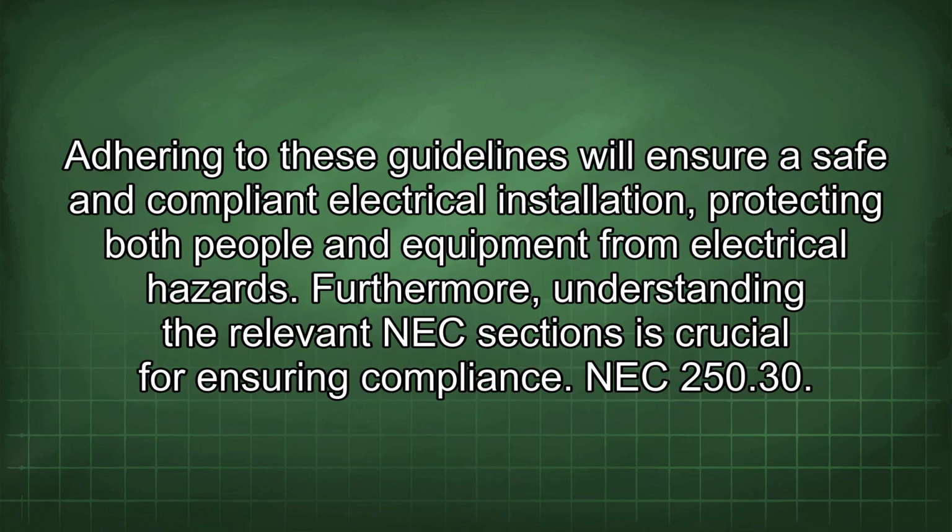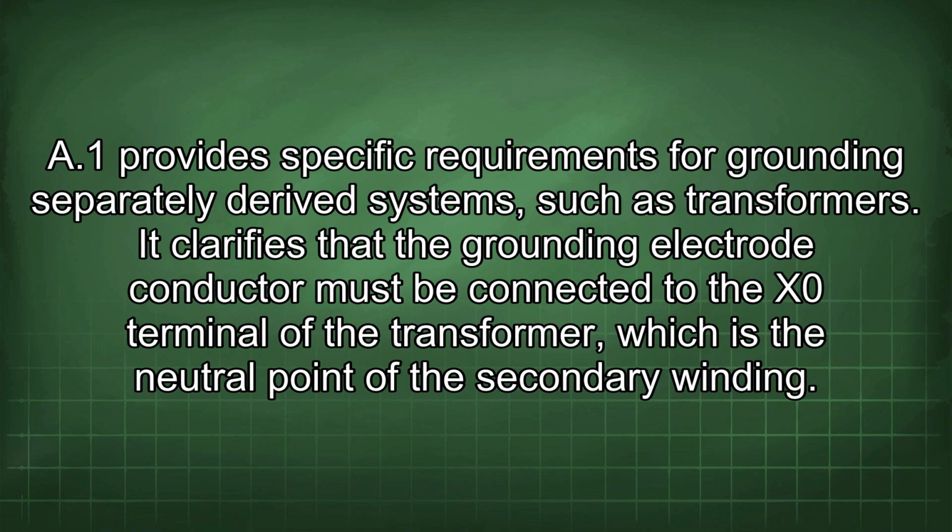Adhering to these guidelines will ensure a safe and compliant electrical installation, protecting both people and equipment from electrical hazards. Furthermore, understanding the relevant NEC sections is crucial for ensuring compliance. NEC 250.30(A)(1) provides specific requirements for grounding separately derived systems, such as transformers.